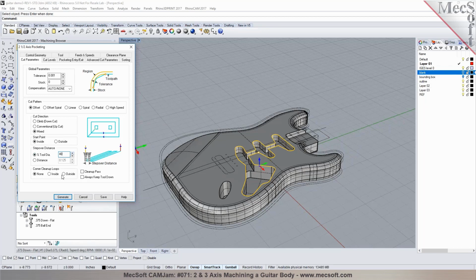And which means what? What does the step over mean? Right here, if you look at this picture, the step over distance is the distance between the paths inside of the pocket. Okay. So they would probably basically overlap, right? Well, they would be offset. I have it set to offset, and the pattern will offset from the outer perimeter. I'll show you what it looks like in just a second.